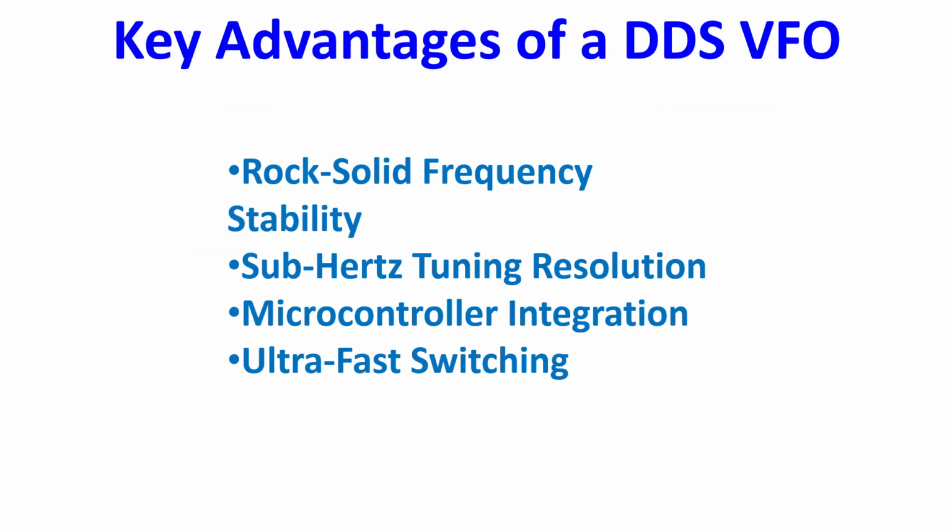Key advantages of a DDS VFO. Rock solid frequency stability. Traditional analog VFOs are prone to frequency drift caused by temperature changes affecting the inductors and capacitors. I have experienced this very much during my initial era of homebrewing. A DDS VFO inherits its stability directly from its master crystal oscillator, often a temperature compensated crystal oscillator or TCXO, meaning it virtually never drifts.